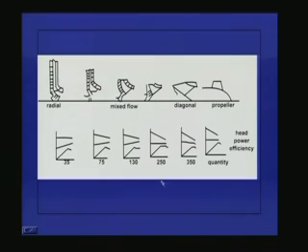You can see when the specific speed is low, the power increases with the discharge on the x axis. So, if I want to pump more water and I open my delivery valve, then I will be increasing the load on the motor. This has to be considered properly while selecting the motor and designing the motor.